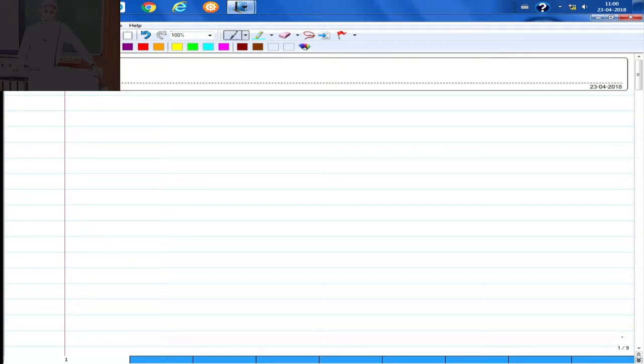They will modify your stiffness matrix and also the right hand side. Modification in the stiffness matrix, because of the contact conditions, the stiffness matrix will change. And the right hand side can also change, because of the force contribution.